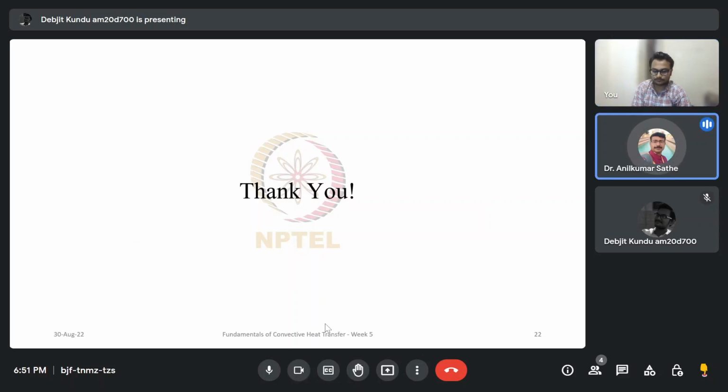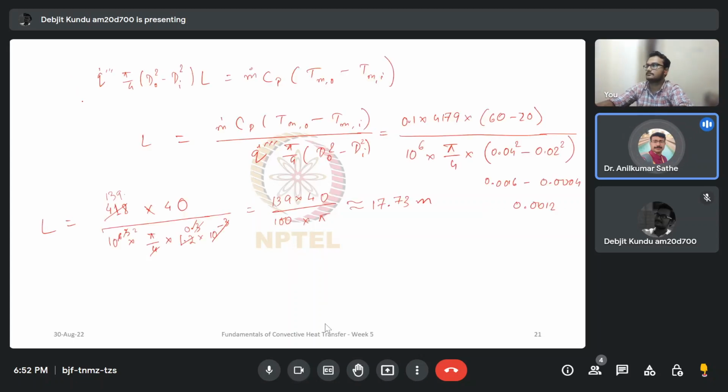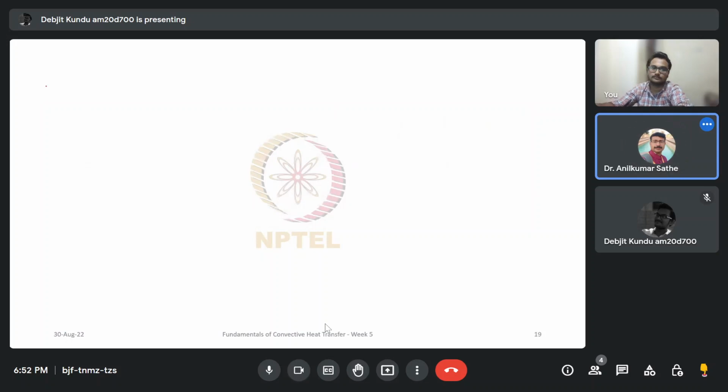No, before that, another question, sir. If the velocity profile and temperature profile both are given, and I want to calculate the bulk mean temperature. I have seen one formula, but I am not getting it, because in the derivation that sir has explained, there is one formula, that is the increase in internal energy, with CpT and an integration sign. Actually, this is the condition of parallel plate channel flow.